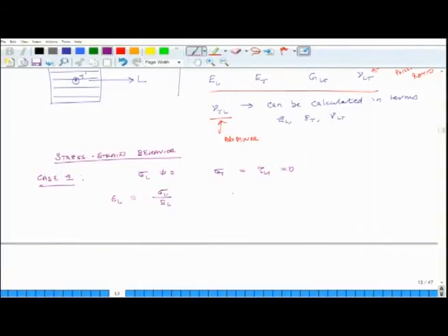And because the thing becomes a little longer, it will also become slimmer because of the Poisson's effect. So, the transverse strain epsilon T will be what? It will be minus mu LT times epsilon L. Why is it mu LT? The first subscript tells us the direction of the loading.